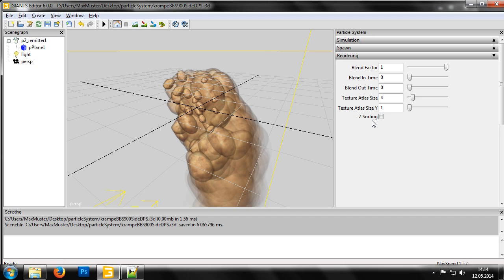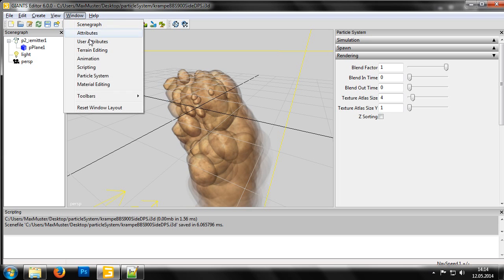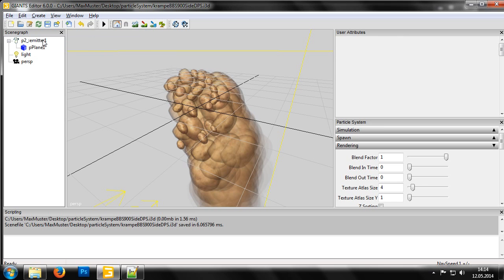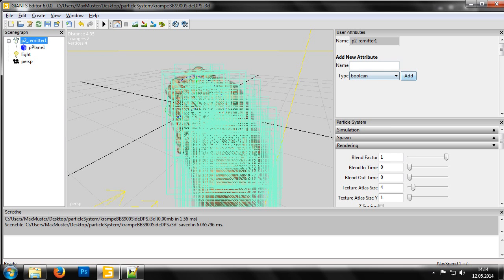To finish off, we have a final tip to help you fine-tune your particle behavior. It is often the case that the particles are intended to closely follow a specific path along a vehicle and not stick to their physically correct trajectory. To combat this, we can set a user attribute to influence the behavior. So we can create a user attribute of the Boolean type with a name useWorldSpace in the particle system node.